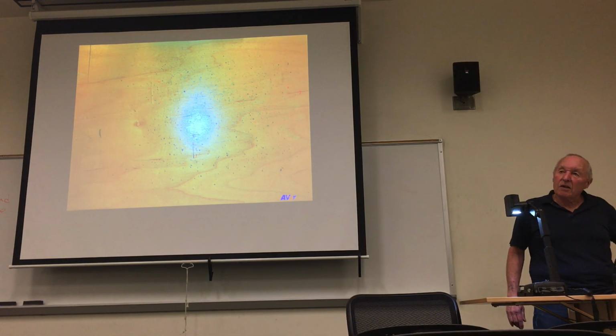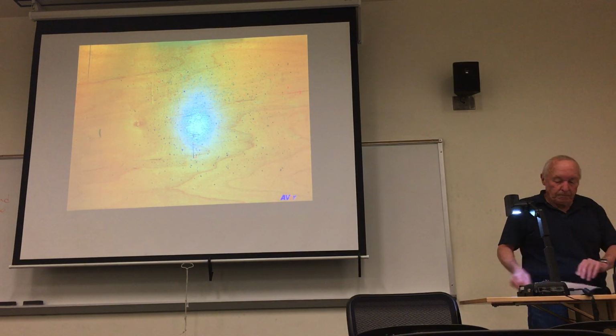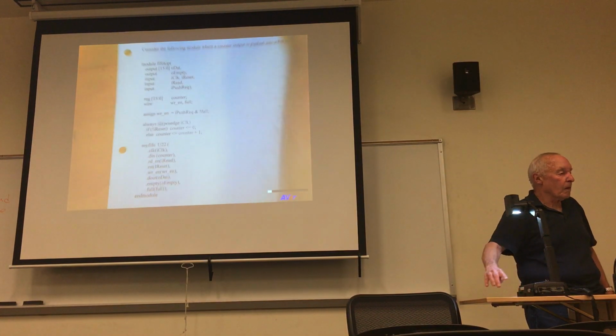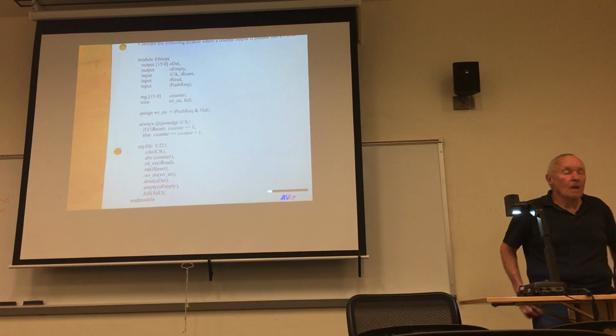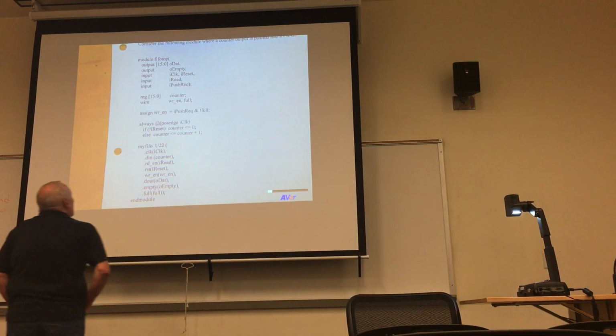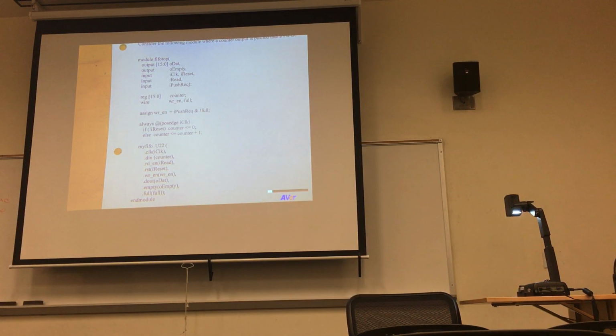So to illustrate this concept, I want to look at an example. I have a module there called FIFO top. I've got some declarations. And you'll see in the always block there that I've implemented a basic counter. If the reset is a logic 0, the count is forced to 0, otherwise the counter increments.